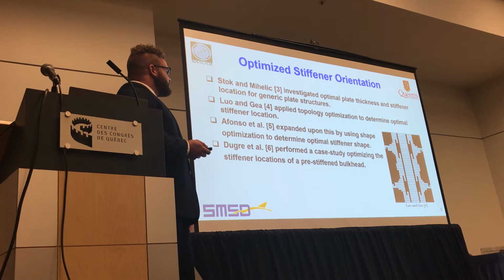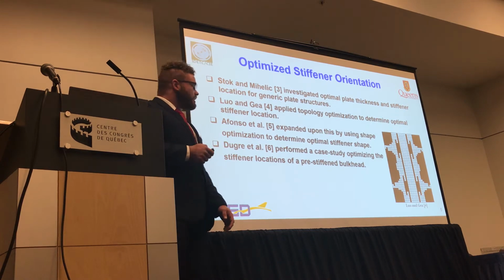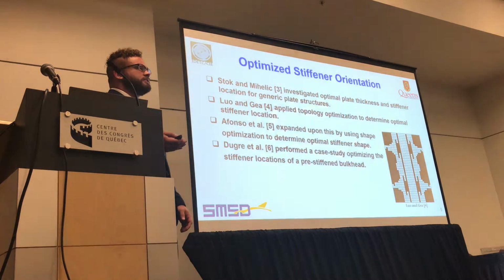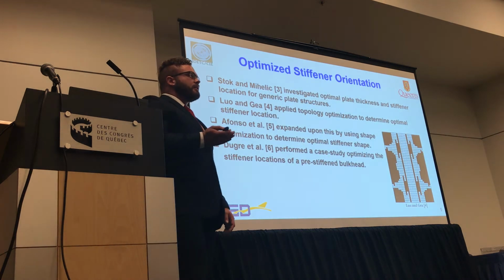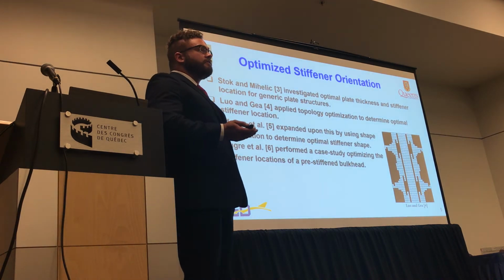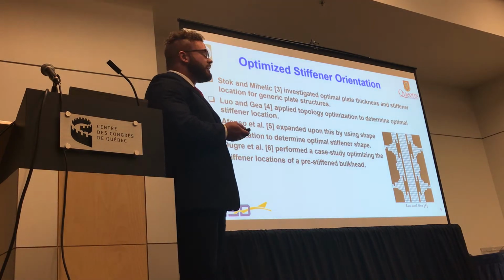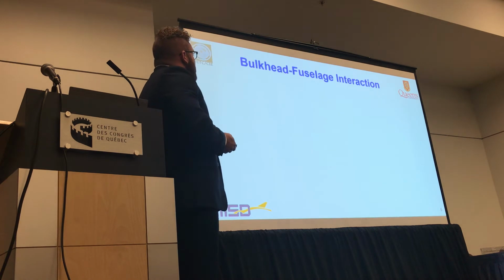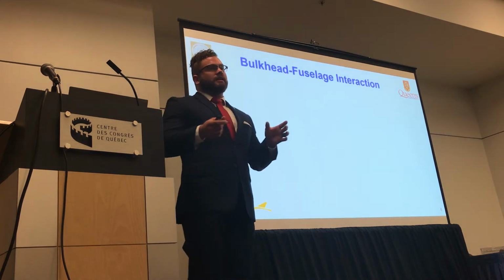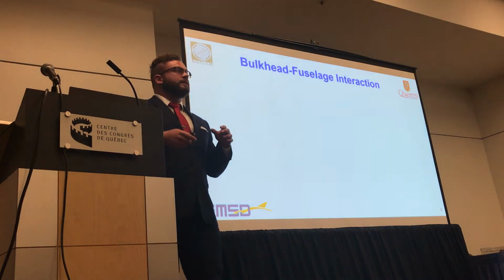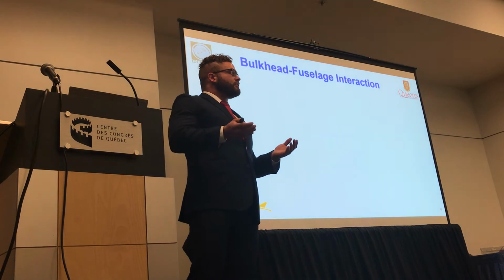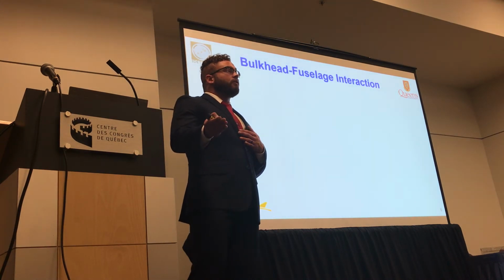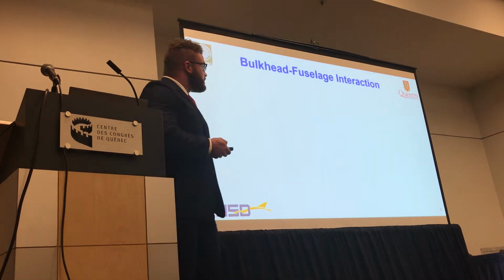So in 2016, Duker et al. were the first to perform a case study investigating a topology optimized bulkhead configuration against a pre-stiffened bulkhead, and they were not actually able to show an increase in performance using this methodology. Another limitation of investigating the bulkhead in isolation is that we're not really sure how well it actually performs when it's implemented in the aircraft.